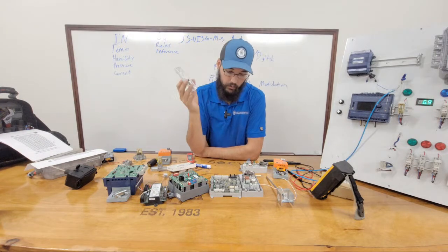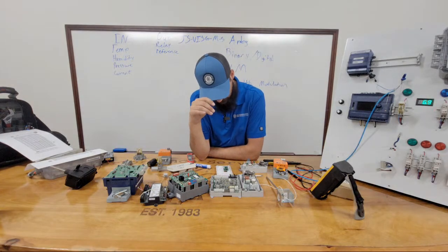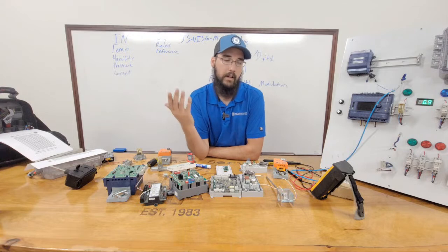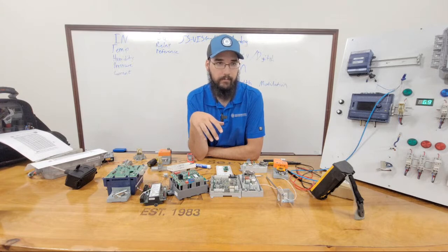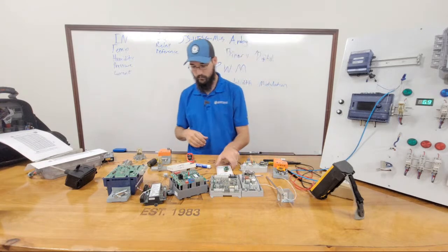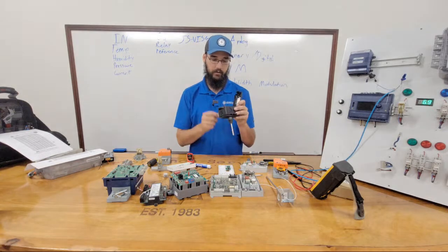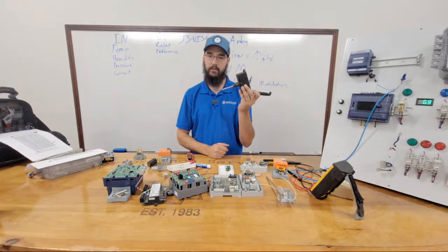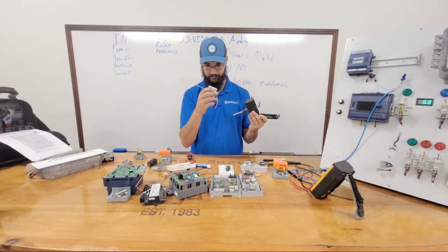But these are just a 2-wire, so this would be an analog input device. The controller is doing nothing more than just reading ohms through that thermistor, and then it's converting that into a temperature via the chart, and off we go. Front end gives you a temp. Same exact thing that is happening here with these. You just have 2 wires. This would be one that could mount on water. You could mount this on duct. Typically this style, this is a Johnson setup.